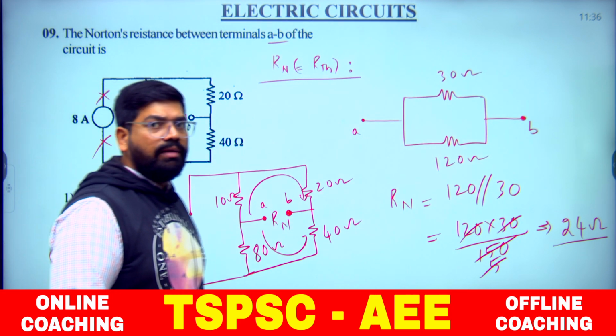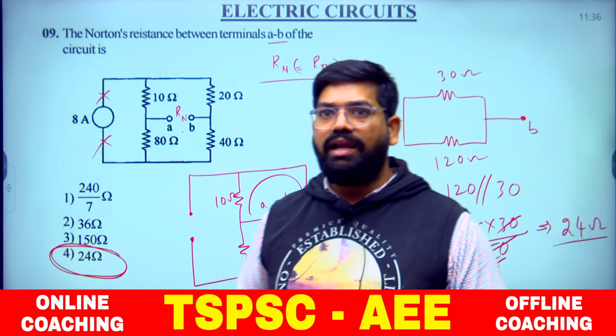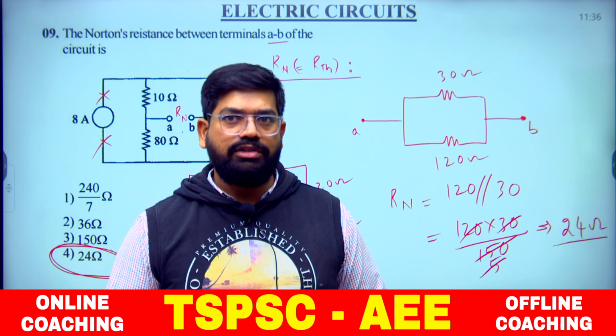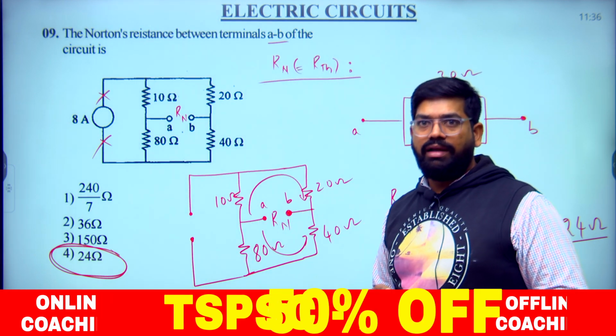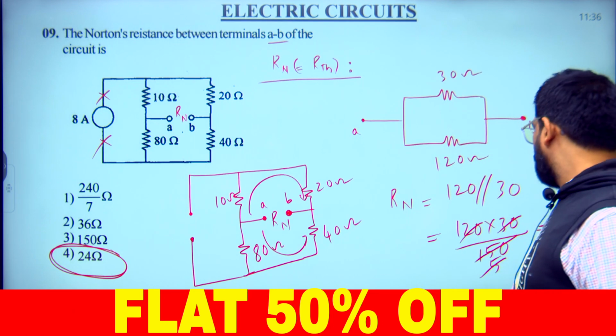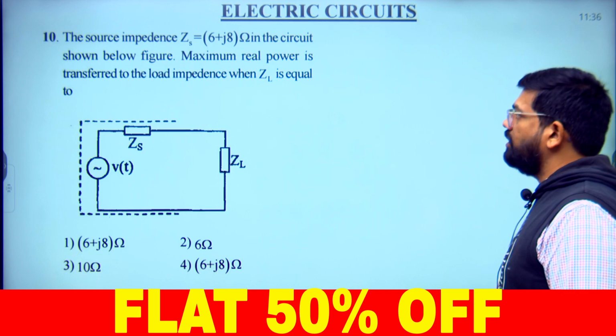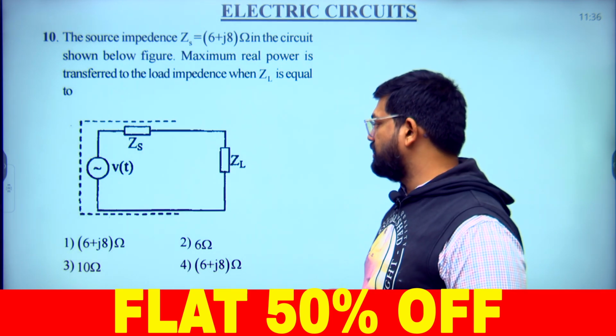Understood? You have to be careful where the sources are present and how to deactivate the sources. A current source must be open circuit and a voltage source must be short circuit. Now move on to the next question. Here the question is related to maximum power transfer.